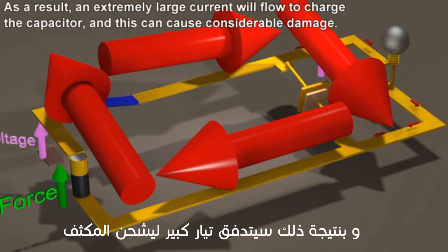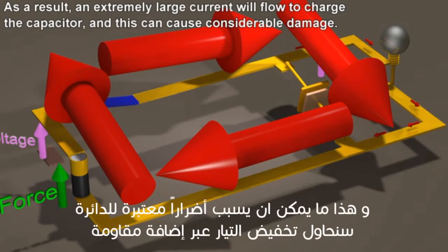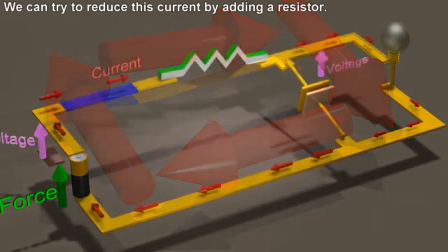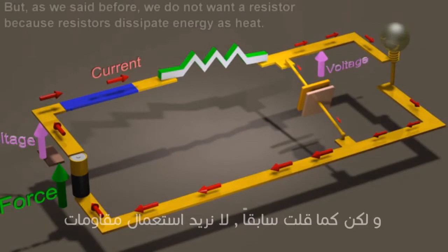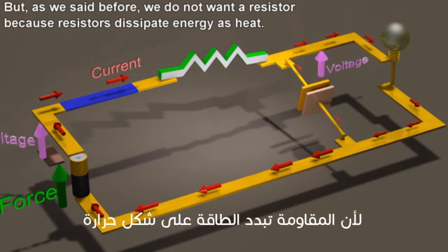As a result, an extremely large current will flow to charge the capacitor, and this can cause considerable damage. We can try to reduce this current by adding a resistor. But, as we said before, we do not want a resistor because resistors dissipate energy as heat.